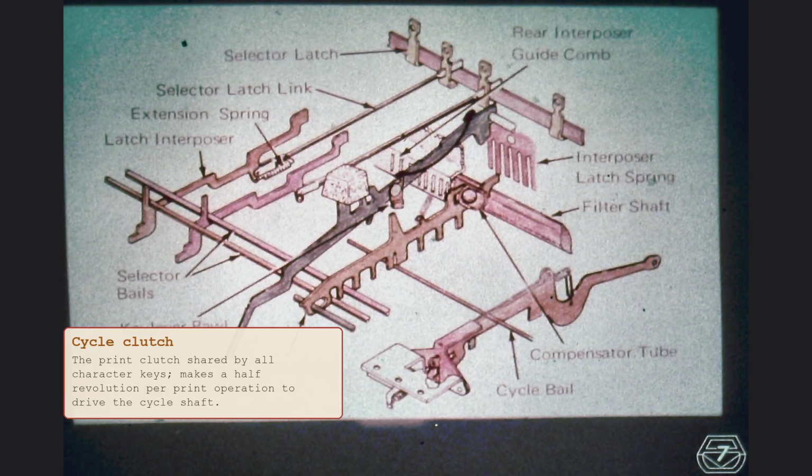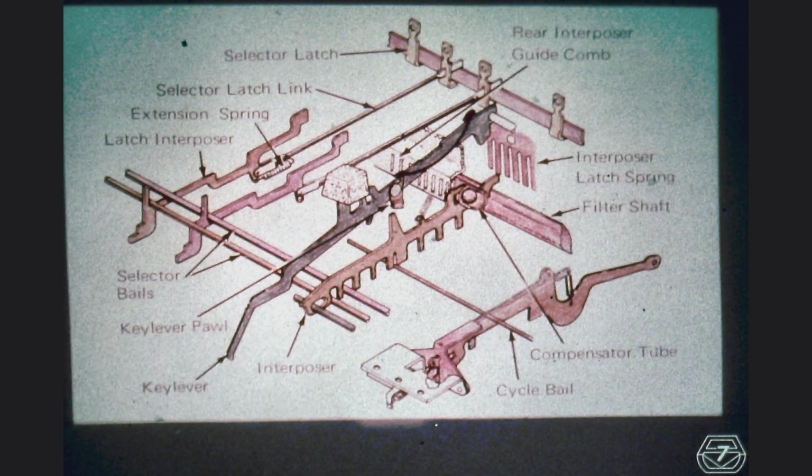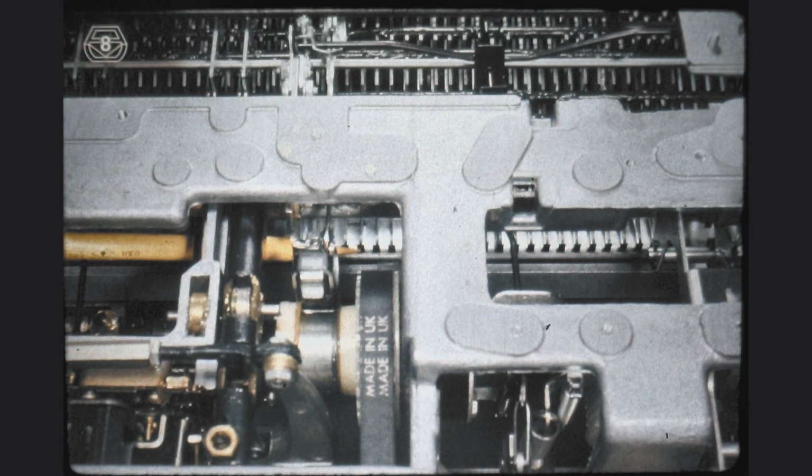As we studied in Program 10.1b, before moving on, you should attempt to find these parts on your machine. You can find them even without our help. Be sure to also learn all the new names of the parts. By tilting the machine on its back by about 120 degrees, you will be able to locate the indicated character interposer latch springs and observe a latch-down interposer, as shown here. As mentioned, the latching down of the interposer is really all there is to the presetting of the latch selection.